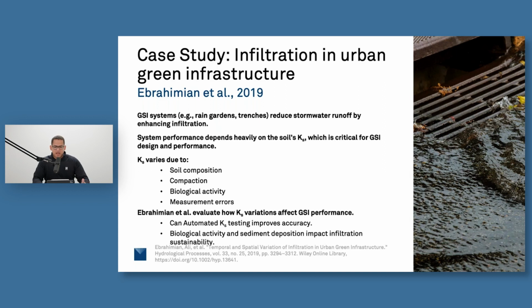The infiltration capacity of these systems, of course, is influenced by the soil's saturated hydraulic conductivity, and this is a critical component in GSI design and performance that we need to understand. However, KSAT varies significantly over time and across different locations within GSI systems due to factors like soil composition, compaction, biological activity, and measurement errors as well. And we'll talk a little more about that as we dive deeper into this.